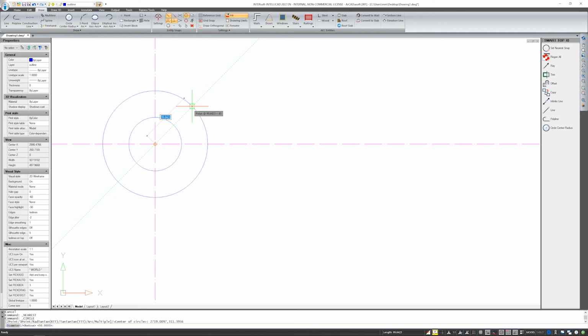Remember that when you draw, you can turn on the snap point that you need, and the rest will be automatically turned off, and you'll be able to safely select the point that you want. Now 2 circles have been introduced on the same center. The other snap points that are often useful are the symmetrical point, which is the exact center of the line, or the center of the arc, for example, and this is not the center of the arc, but the center of my piece of the arc's contour.